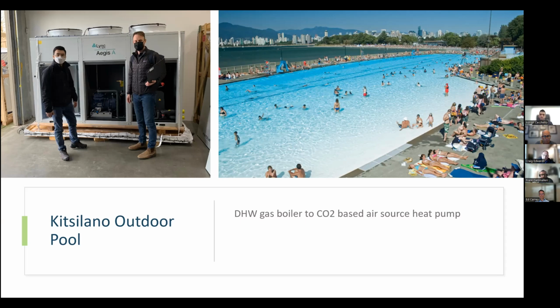No, that's great, Craig. Thanks for the background. A common theme that we're hearing from you is that you really have to be mindful of trying to avoid the cycling. So it's good that you've taken that into consideration in the design. The reverse flow piping that you referred to is a good way of dealing with that. A note to the audience is to be mindful of that as well, and to get to know the efficiency in the operation of CO2 in particular. It really likes to see that colder water to operate effectively. So some great tidbits of information here.